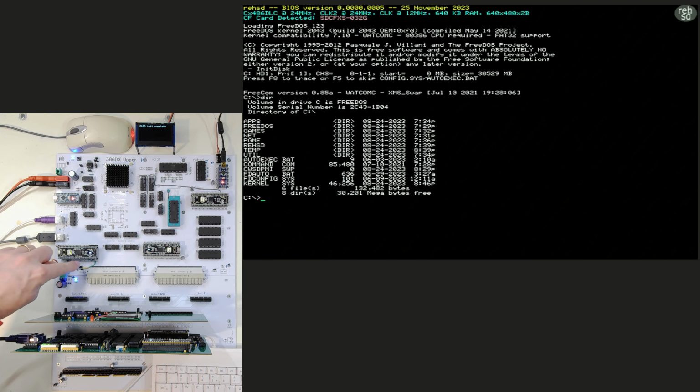If I flip this switch, I can double that, and right now what I would expect is that when it gets to the CF card I/O, it will stall out at that speed. So most likely I have work to do, either to modify wait states for this specific address, or update my code and add in possibly delays at certain locations, because I think most of it is that I'm just trying to access that CF card too quickly.